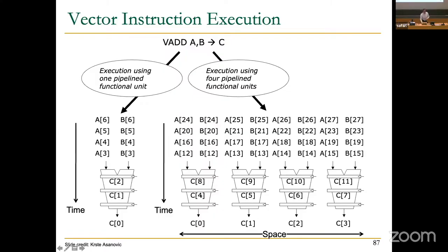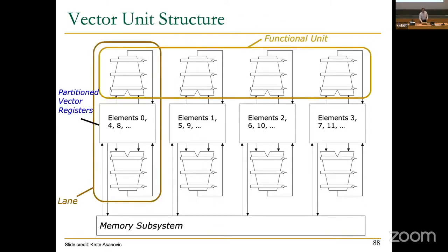That sounds good. Now you can also customize the register file. Elements that are numbered 0, 4, 8, 12, 16, 20, 24 go to this one. The other ones go here. Basically, there's a mapping, a partitioning of the register file across these functional units now. Not all registers need to feed all functional units. This makes it a little bit harder to program also, later. So basically, this is what a GPU kind of looks like today.